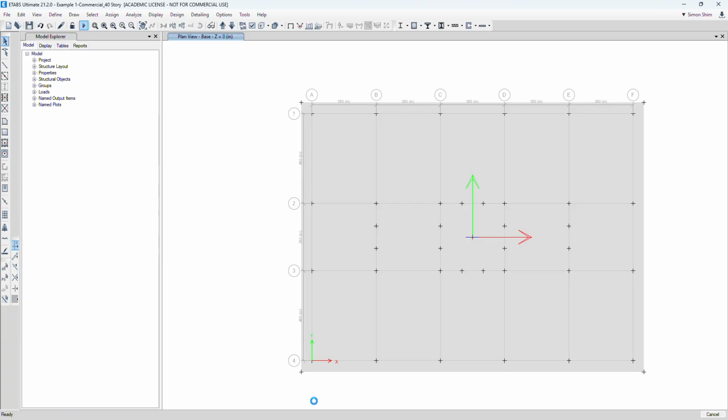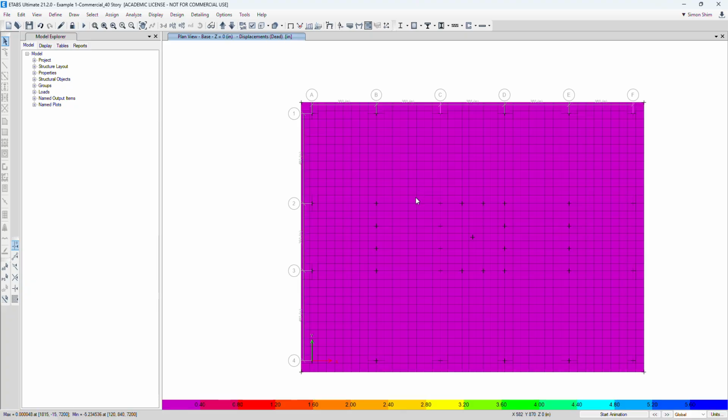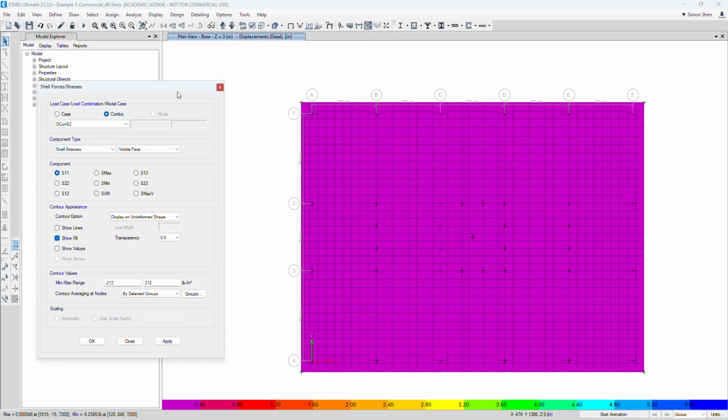When you estimate all the design forces, you check the shear and the bending at the same time. In these cases, we are currently checking the shear stress is beyond our allowable concrete shear strength significantly, so I decide to increase the mat thickness. So I increase to 8 feet.